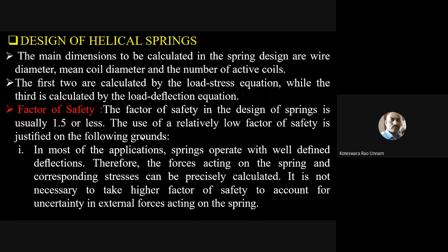Like already told, we use this factor of safety to accommodate unforeseen effects. Here in case of the springs, the uncertainties are very less. So that's why we use a low factor of safety.